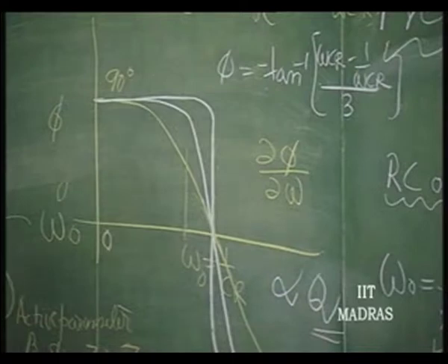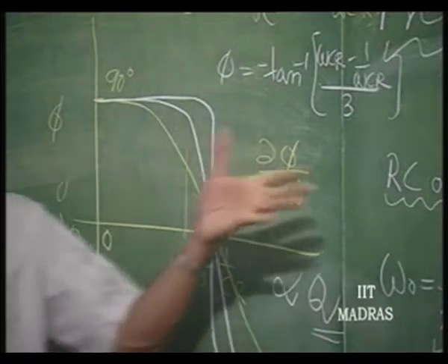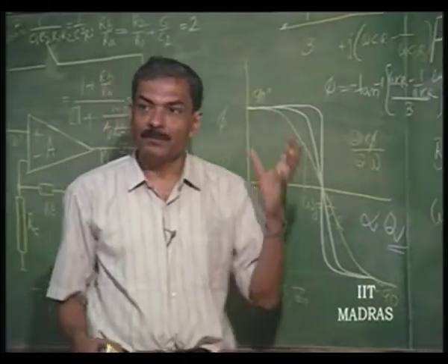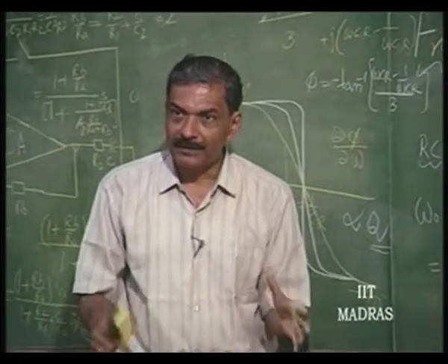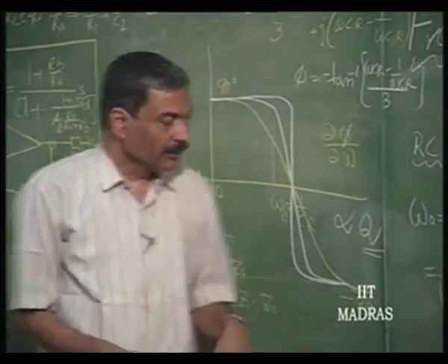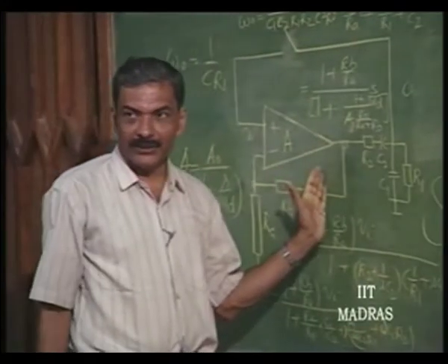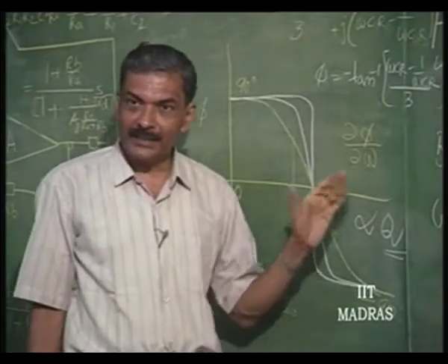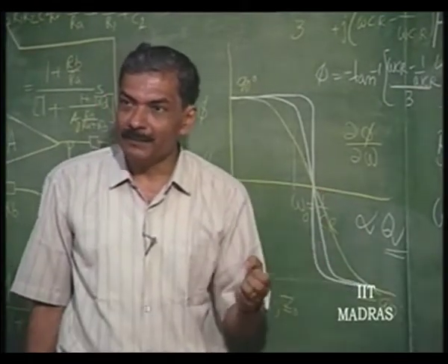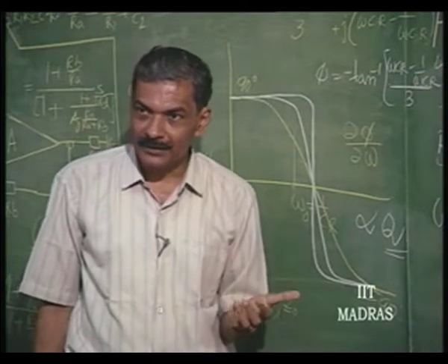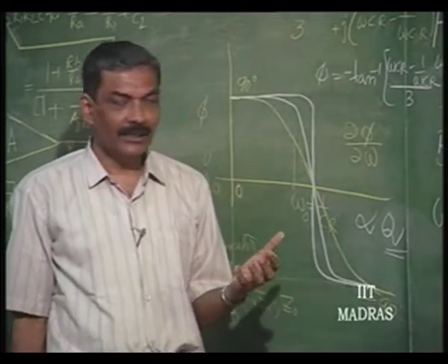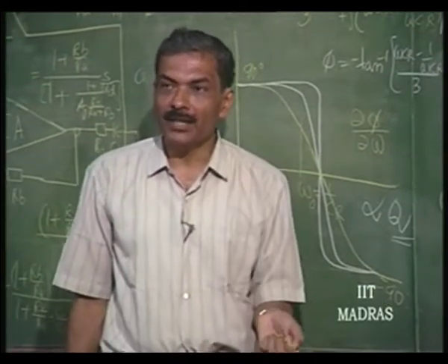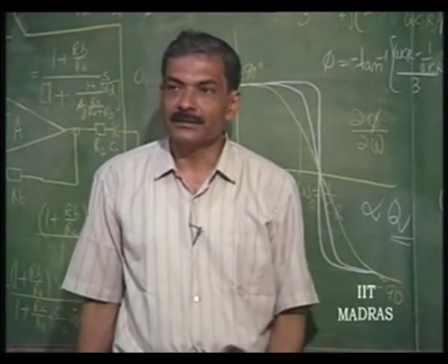phase variation, right? And that is why the frequency stability of any oscillator directly depends upon the quality factor Q of the passive network that composes the frequency determining network. So, irrespective of the device that you use, in the case of a crystal, apart from the phase varying so rapidly, even the magnitude of the impedance goes from 0 to infinity. So, this facilitates the crystal being used in the loop, and invariably the crystal oscillator oscillating at the crystal frequency, right.